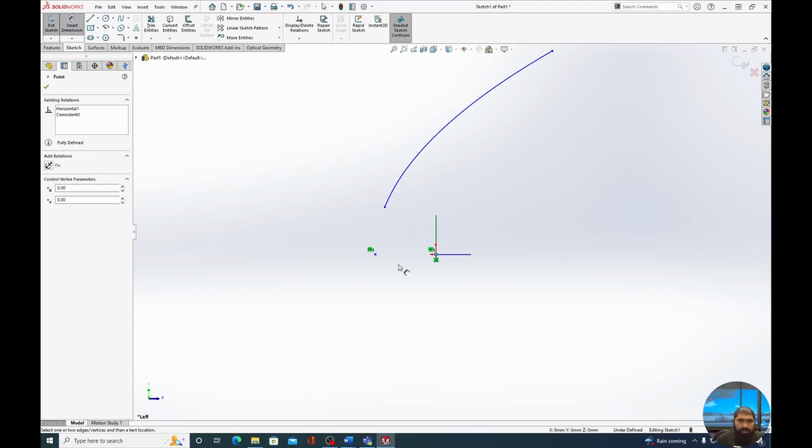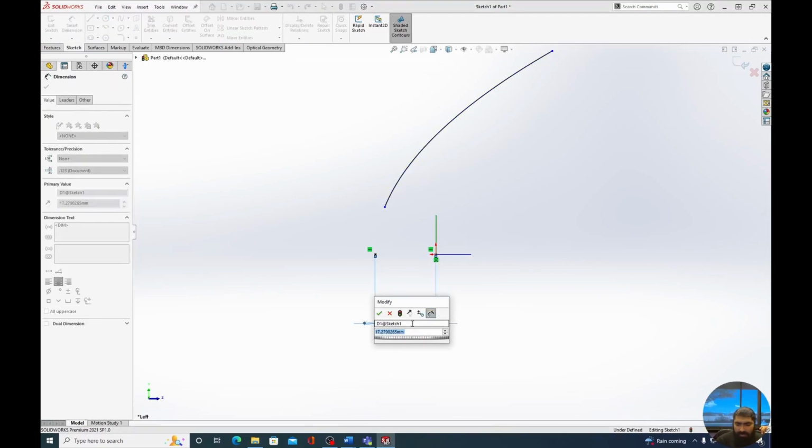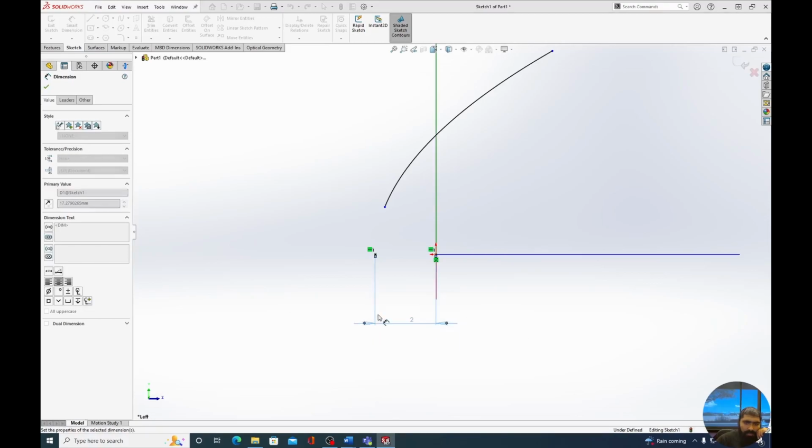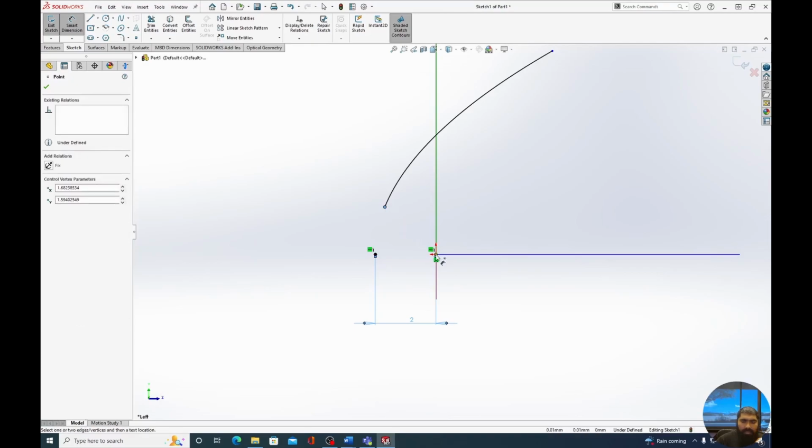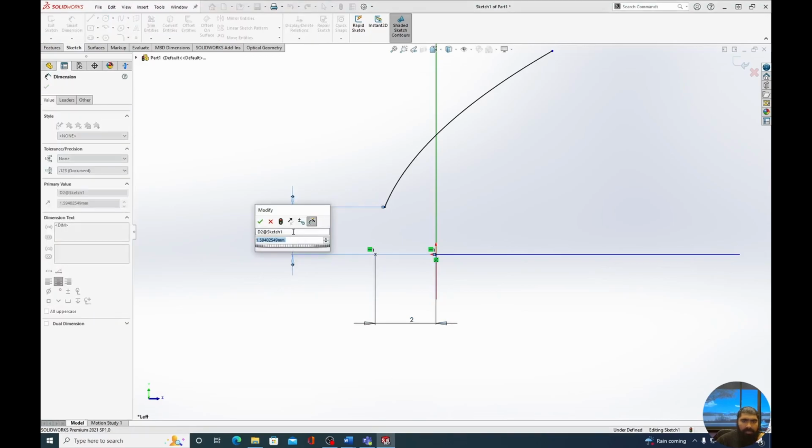The first distance we're going to put is from the bottom of the parabola all the way to the focal point. I call this the bottom because if you've learned parabolas, you usually deal with them upwards like this. So I'm going to set this distance to 2 millimeters and press OK. The next parabola distance I'm going to have is between here and the bottom. So top to bottom, this will be 4.